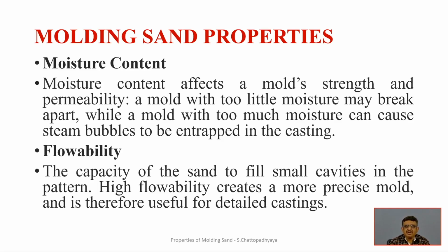And in order to ensure that the sand is appropriately distributed into the very complex, complicated profiles of the pattern, one needs some flowability. If the flowability is not there, because of the moulding and ramming, the sand particles will not be spread across the surface of all those patterns, and if there is no sand adhered to the surface in those intricate parts of the pattern, the problem is that the formation of those curvatures and shapes will not be generated. So everywhere in that thin layer, whatever the form design part of it, we have to ensure